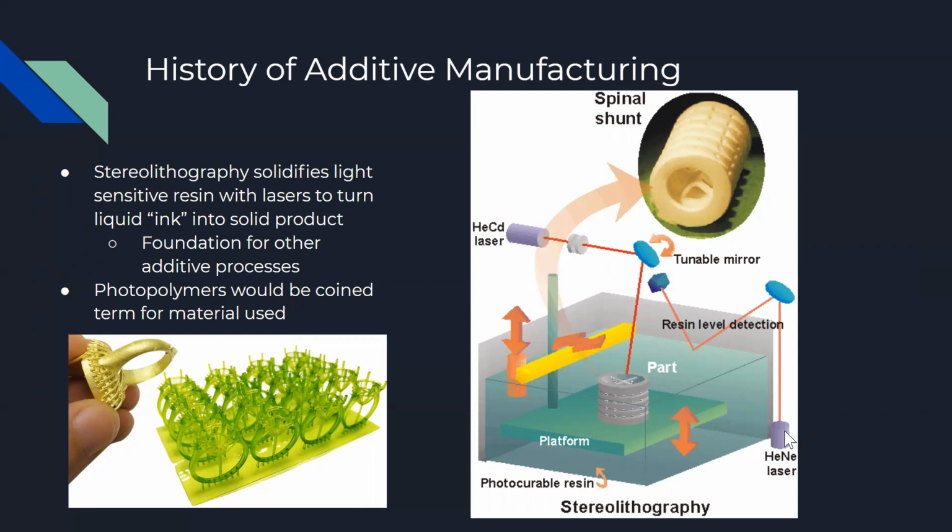And then after that, a new layer of liquefied resin is added on top in a very thin manner, and then this is struck again by a laser, which then again hardens it. This process is repeated over and over, going layer by layer with very small thicknesses until the final part is created. Now, there's a platform beneath the resin basin that adjusts to each new layer of resin, so it moves down as the parts are solidified into its final shape.